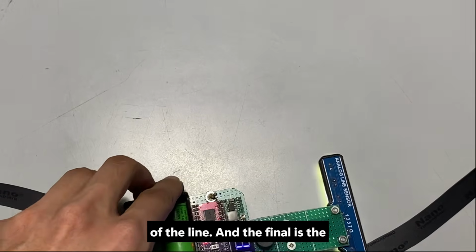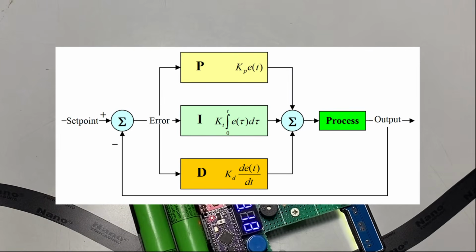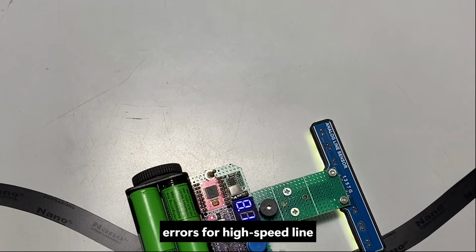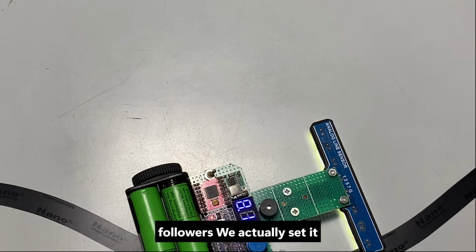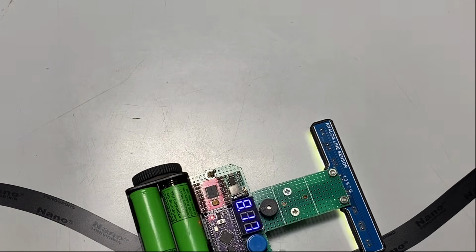And the final one is the integral, which means I. This is the memory. It looks at the past errors. For a high-speed line follower, we actually set it to 0 because the robot moves too fast to care about the past.